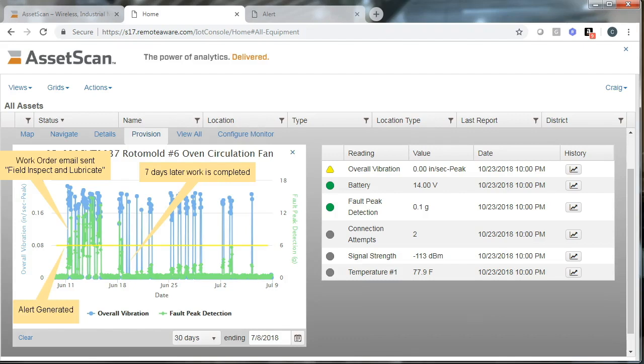So that kind of wraps up our case review for today. In review, we demonstrated the complete value chain for predictive maintenance by adding a sensor, generating an alert, generating a prescriptive task, and completion of work. This avoided a larger failure of permanent damage to the bearing, which avoided the increased shaft deflection and ultimately the fan rotor contacting the shroud, causing significant collateral damage.